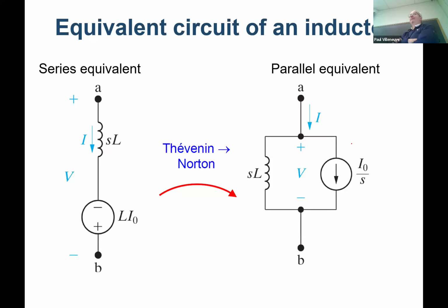There's a reason. Is it because it's part of the differential equations for current and voltage across an inductor or capacitor due to time? Well, yes, but you'll notice I flip-flopped, right? One's the current, one's the voltage. Why did I use current for the inductor and voltage for the capacitor? Well, you have to, because there would be a discontinuity if you swap them.